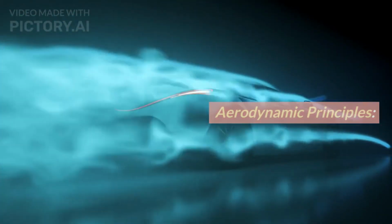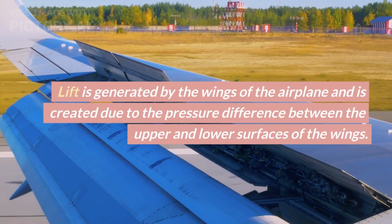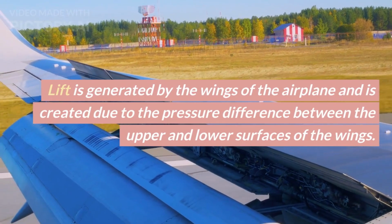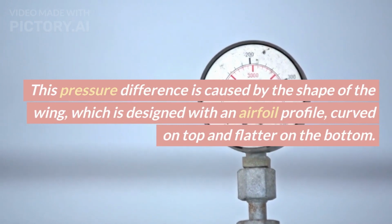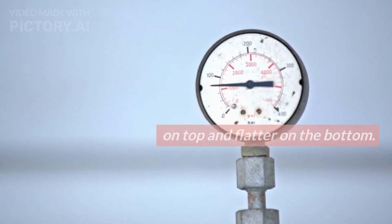Aerodynamic principles. Lift. The primary force that enables an airplane to stay airborne is lift. Lift is generated by the wings of the airplane and is created due to the pressure difference between the upper and lower surfaces of the wings. This pressure difference is caused by the shape of the wing, which is designed with an airfoil profile, curved on top and flatter on the bottom.